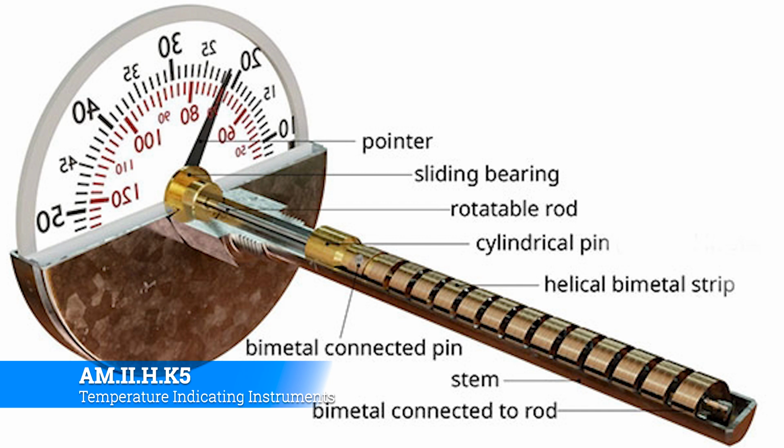Now from that, you can turn around and say, hey, look, this is what the temperature is. This is what our fuel consumption should be. This is what the oil should be doing. This is something we should be worried about. We should be worried about ice. We should not be worried about ice. So on and so forth. Very, very important flight instrument that often gets overlooked because it's so simple. I mean, it's just two strips of metal tied together.